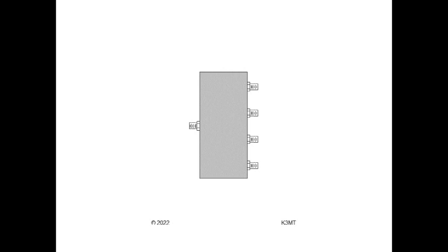The thing is a typical black box. A hacksaw can help open it to see its innards, though this isn't necessary. All we need know is that it scatters the input power to 4 outputs, and, as a circuit, can be described by a set of 25 measurements, called scattering, or S, parameters. When we put power into it, part goes into each output load.